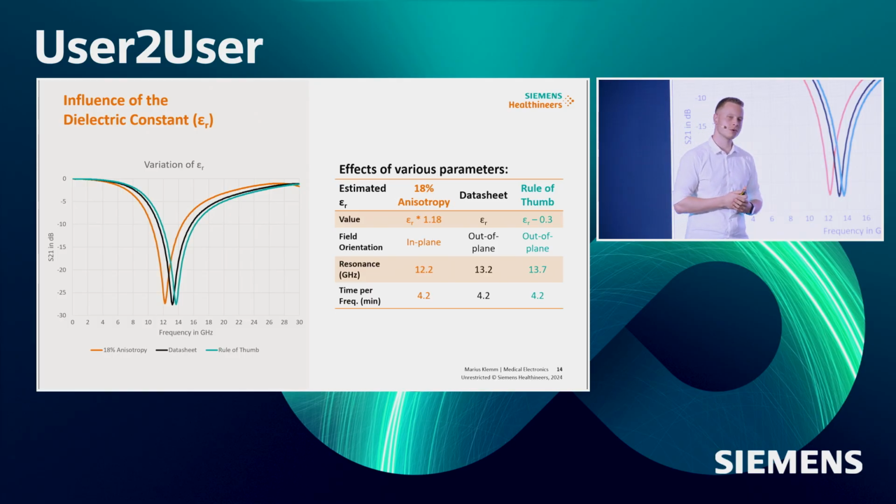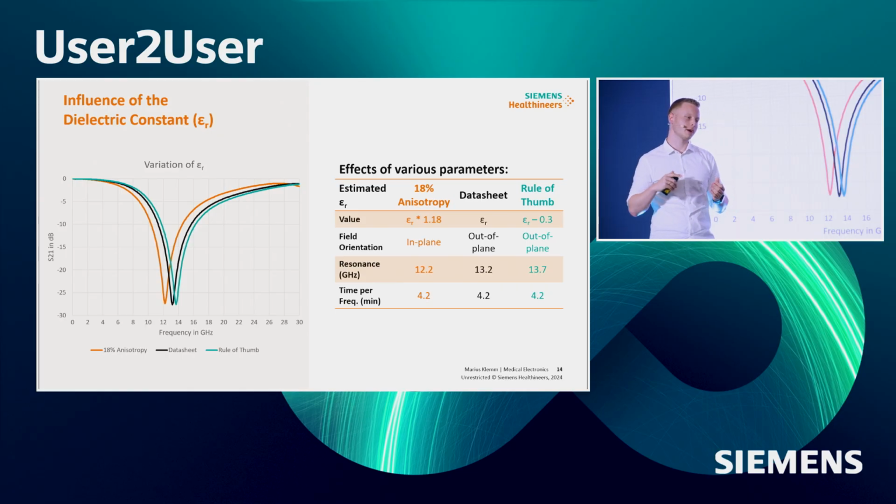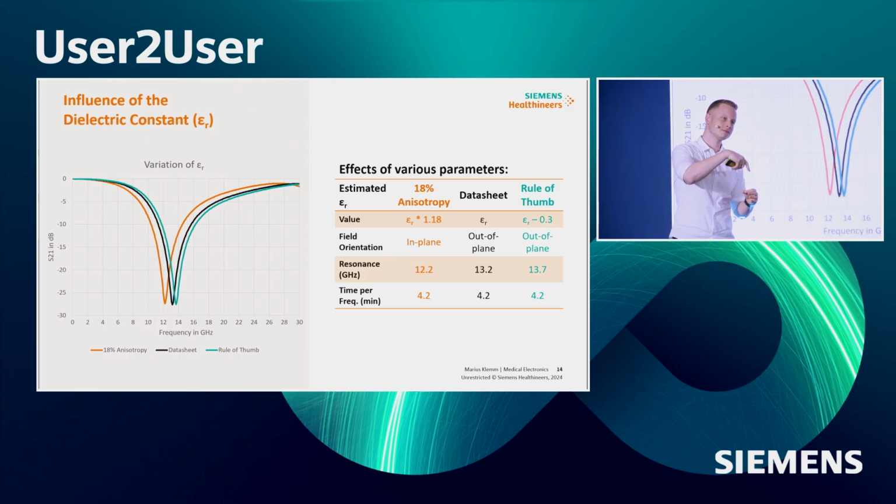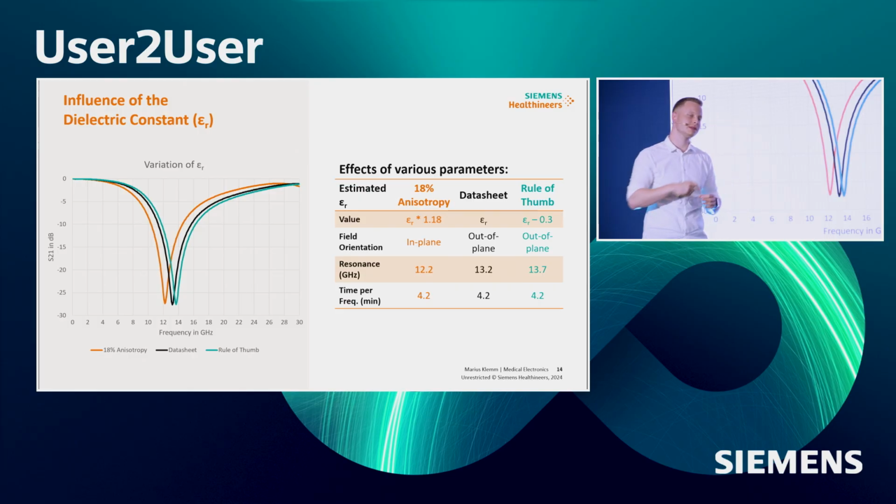It's called the anisotropy. The reason behind that is it's larger for the via than for a transmission line, because in the transmission line in the PCB, the electric field is directed in the Z direction, so to the bottom through the PCB.